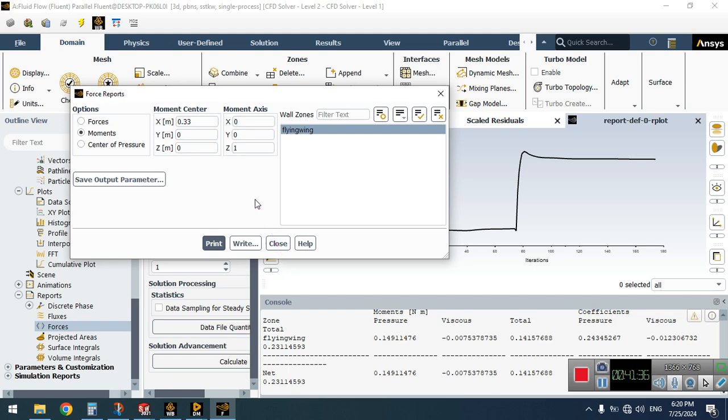So at 0 or at 5 degrees of angle of attack, the point where the pitching moment is neutral or near 0 does not change. For both cases, the neutral point is about 33 centimeters behind the tip, behind the head of the plane.